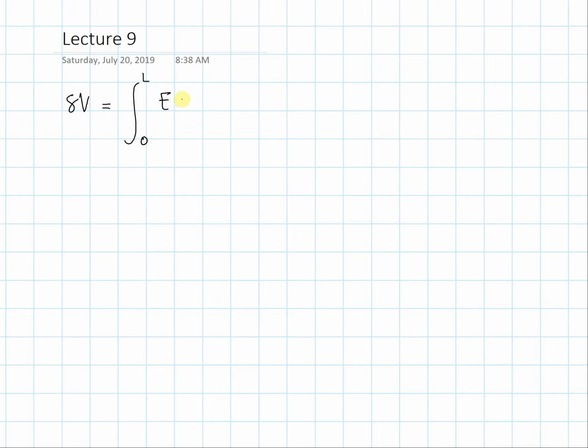This time, because we're dealing with lateral deformation, we're dealing with the moment of inertia. In the last example, we dealt with areas. This time, it's the moment of inertia. So we have V double prime, delta V double prime. Again, when we mention the V double prime, we're always thinking about the curvature. So we're thinking about curvatures in the potential energy strain energy equation, and that's what we have.